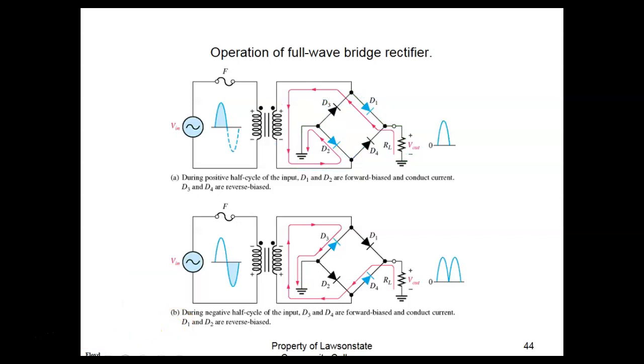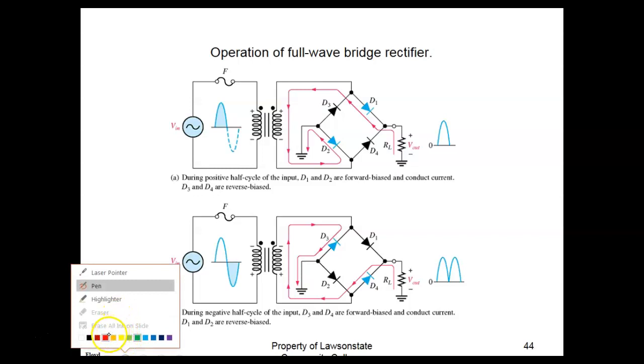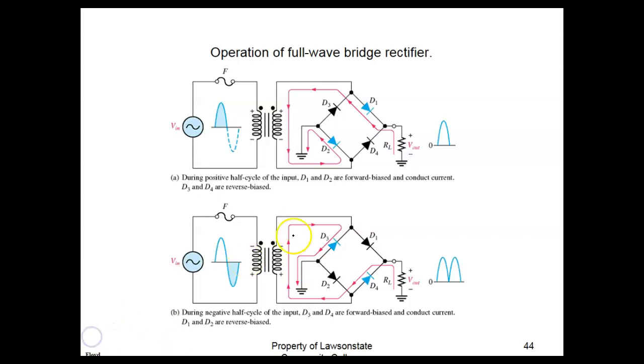So during the next alternation, it's going to switch, which will be the bottom one. So this goes negative, this goes positive. Let's follow the negative over. Negative is going to set here. It's going to turn this guy here on. Negative setting on the anode, this guy right here is going to turn off.